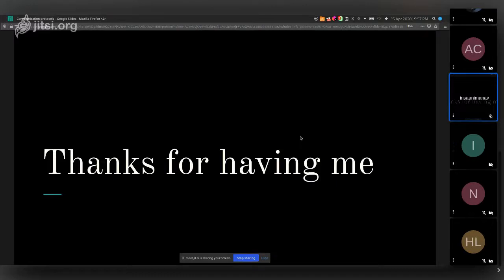I think we should use SPI, since SPI kills 2 birds with 1 stone, because we need a good sampling rate when we are using an ADC. So we need a fast protocol. That's why SPI, and also we need a means of duplex communication. So I should be able to send data to the ADC and the ADC should be able to send the data back to me. Does that answer your question?